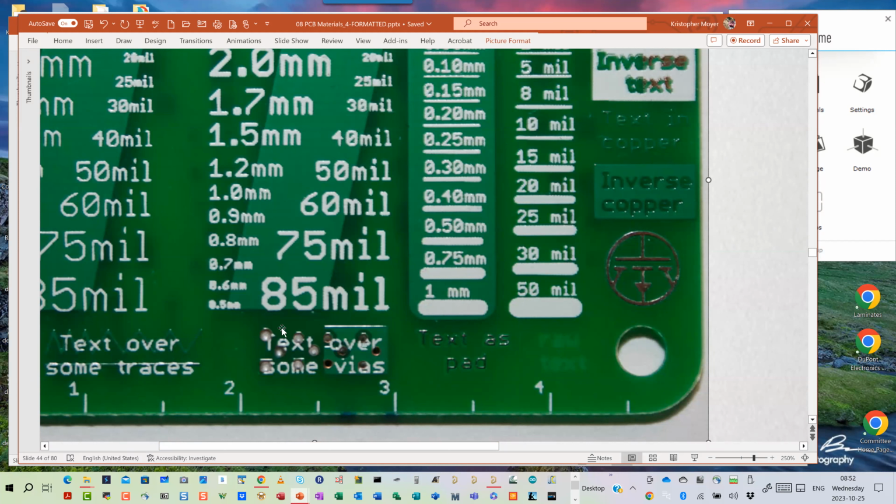Exposed. So anytime there's an opening in the solder mask, exposing my copper below, as in the case of vias or solder pads or anything like that, by default, unless you explicitly tell them not to, your fabricator is going to clip the legend ink off of exposed copper so you have a solderable surface. Any legend ink left on a solderable pad like this will become a contaminant that will prevent or cause a defect in your solder joint formation. So by default, your fabricator is going to remove or trim the legend ink back from all of these exposed holes.